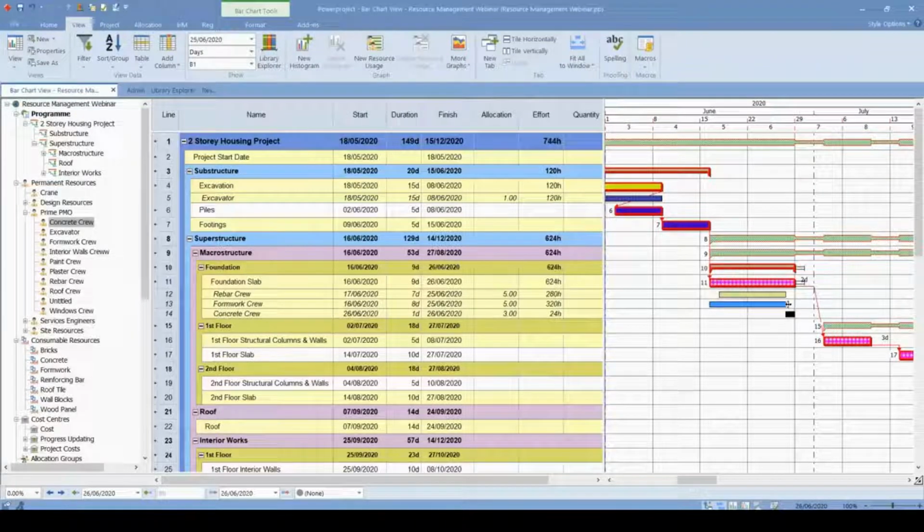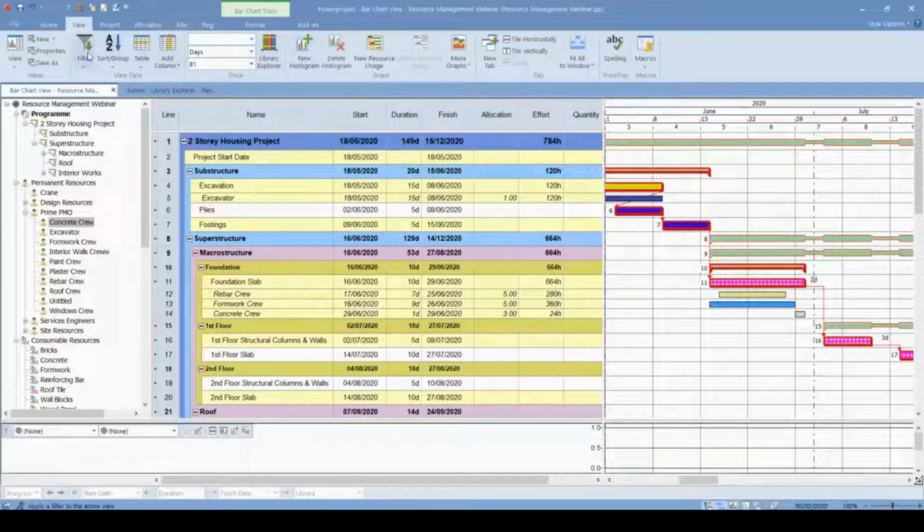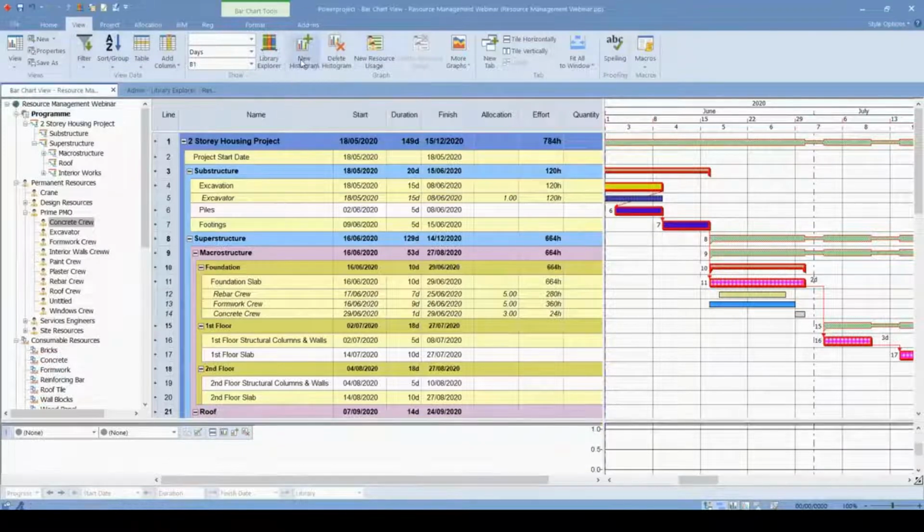This is 8 days, okay, and this activity will be 10 days. So under this 10-day activity, I know that I can actually allocate many crews with the effort on allocation modeling type to determine their man hours differently. And let's go to the right now for histograms. For example, in the view tab we have new histogram tab, and we can add many number of histograms.